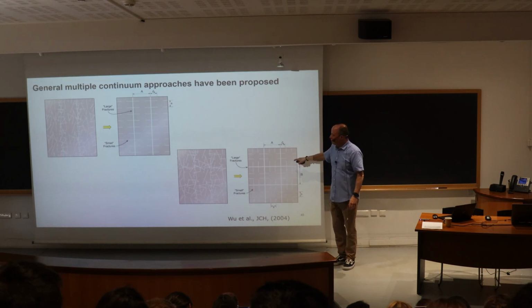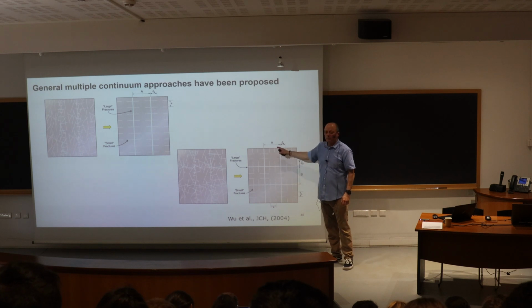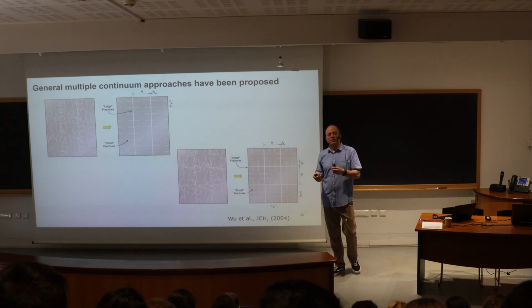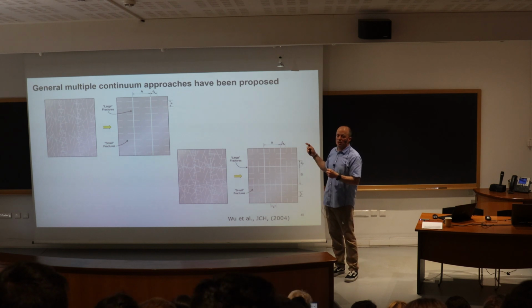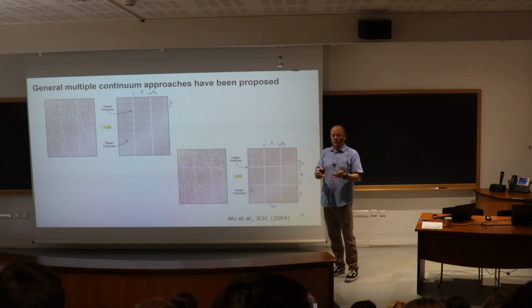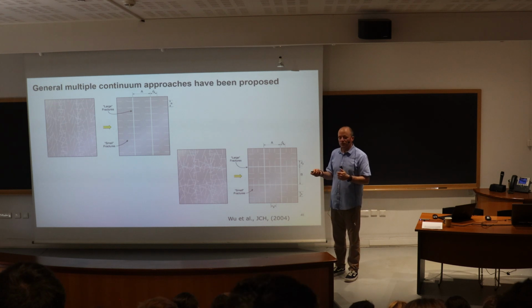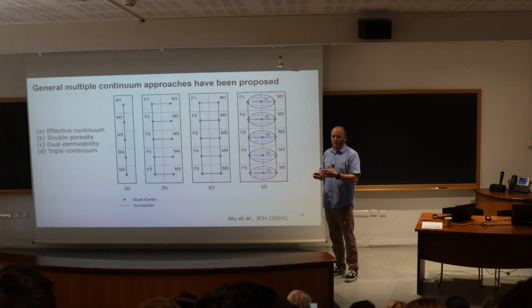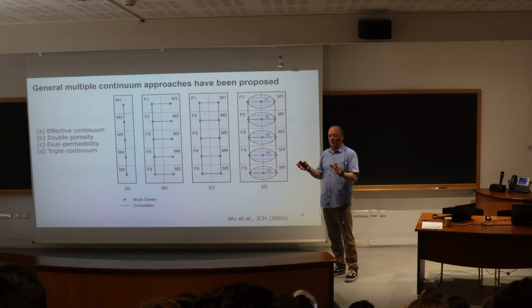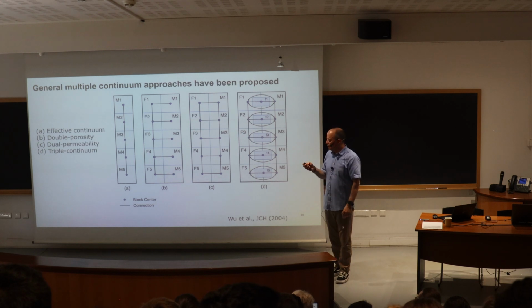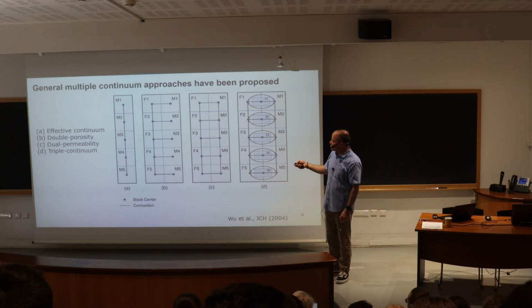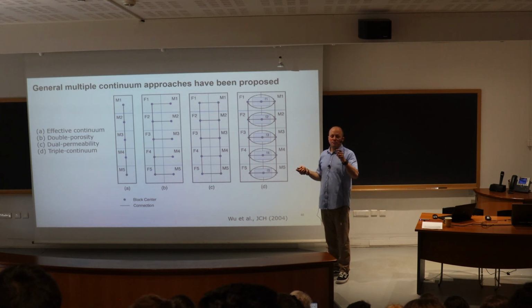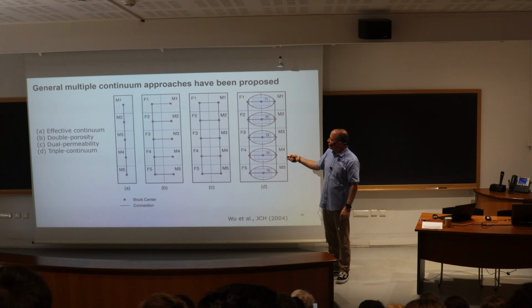And say you would represent your network of fractures like they did here. Like the properties of the fracture, you would take these, say, vertical fractures, you would compute their equivalent hydraulic connectivity from the simple relationships I showed before. You would compute the equivalent porosity, and those would be the properties of your fracture. And the matrix, well, if you have properties of the rock matrix, that's what you would use. You would not use properties of the fractured rock matrix, but only the rock matrix. And in this case, what it shows is that there is no connection between matrix blocks. So there is no flow from matrix to matrix, but there's a connection from the matrix to the neighboring fracture, and there's flow in the fracture network.